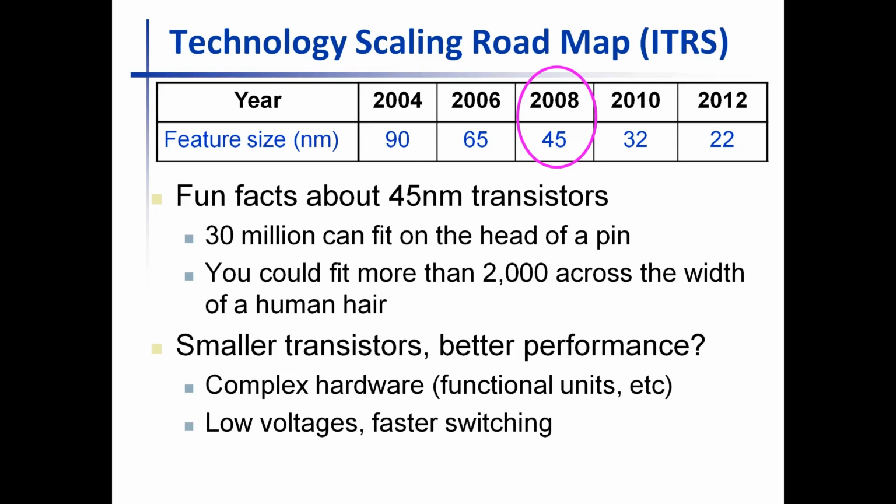The other way is, with the transistor being made smaller, that transistor could be operated with low voltage. The potential of electricity you would need to switch this transistor on and off becomes low, right? Because the width of the channel becomes smaller, so the amount of push you need to operate the gate is less.